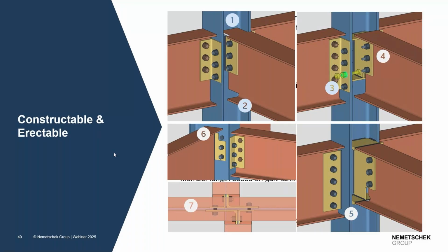There, SDS has provided a cut at the top of the flange, since the column depth and the beam top flange are almost of the same depth. SDS has provided a cut at the bottom of the beam in image number two to have ease of drop down connection. In images number 3 and 4, SDS checks the space validation.